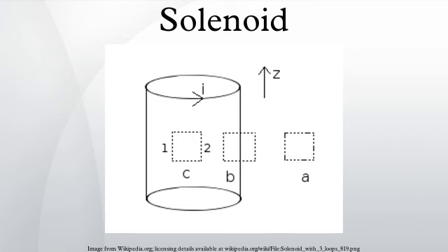The force applied to the armature is proportional to the change in inductance of the coil with respect to the change in position of the armature, and the current flowing through the coil. The force applied to the armature will always move the armature in a direction that increases the coil's inductance.